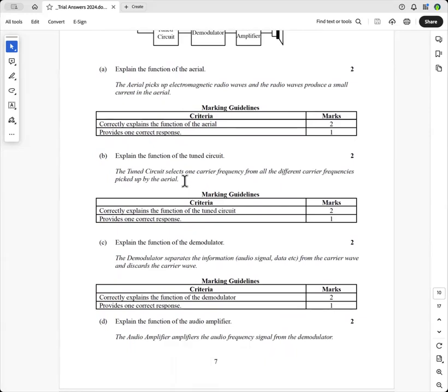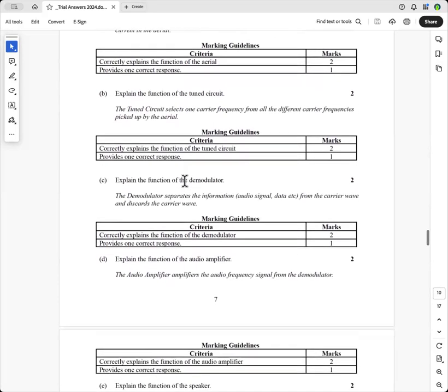And so the tuned circuit is tuned to pick up the frequency of the carrier wave. And you have variable inductors and variable capacitors to get the current at the same frequency as the carrier wave that you want. And you can use a dial or a knob to turn that, or you can use the latest electronics to dial into the resonant frequency.